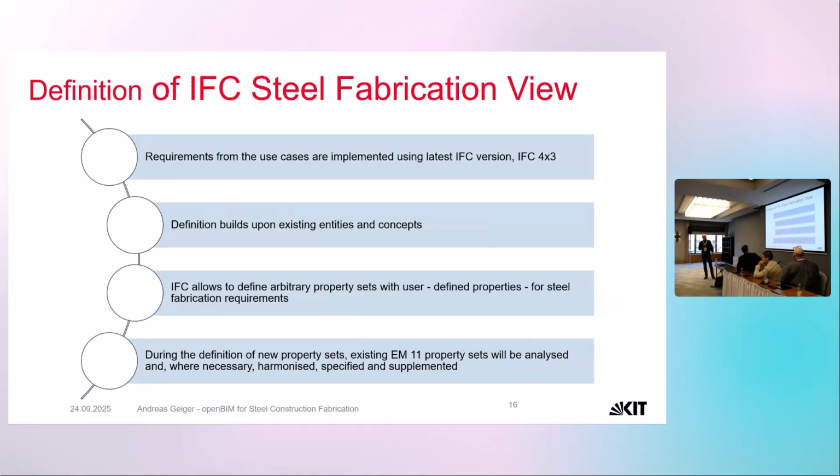So that's the reason why we have started with the steel fabrication view. And the first was we want to have the latest version of IFC, of course. The former definition was based on IFC 2x3. So we jumped to IFC 4. The concept was to use IFC as it is and not to extend the schema, just use existing entities and place all information in property sets.